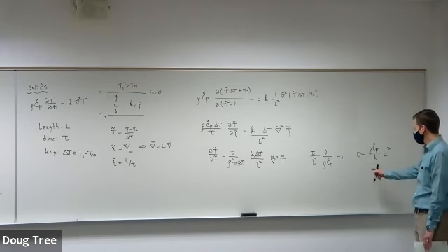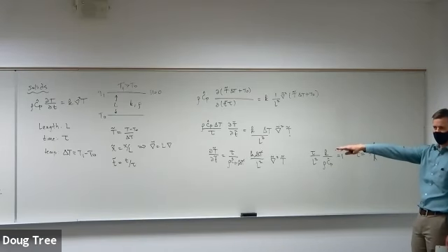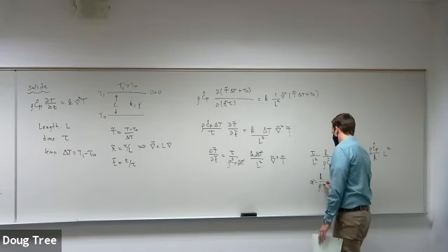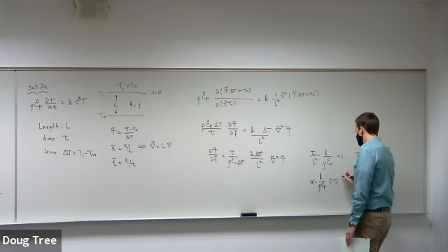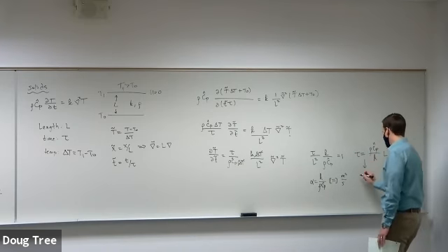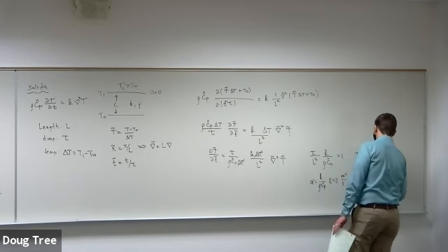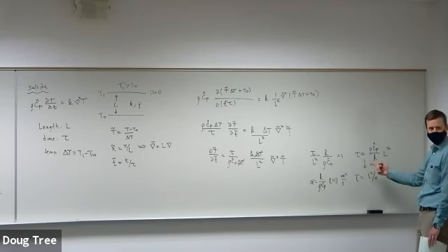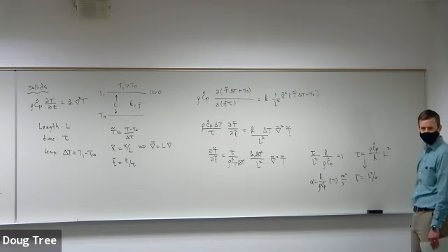Okay, well, do we remember what k over rho c sub p hat is? We talked about it. When we talked about the Prandtl number, you're kind of staring at that. It's not the Prandtl number, it's the thermal diffusivity. Remember, all diffusivities have units of length squared per time, like meter squared per second. So I can rewrite this tau as length squared divided by the thermal diffusivity. So that means I've got length squared divided by length squared per time, which gives me a time in the numerator, right? So length squared divided by alpha is the time, okay?